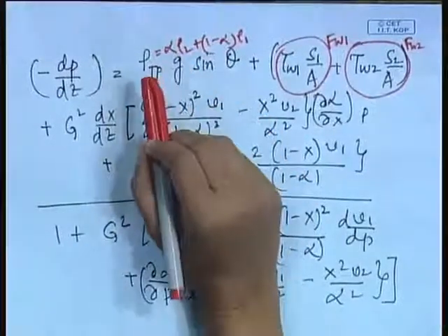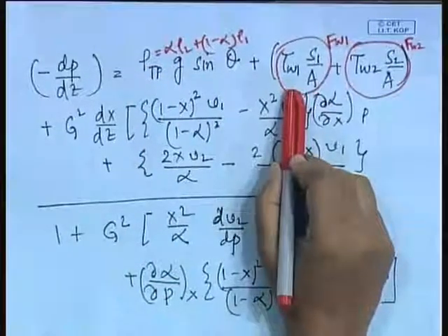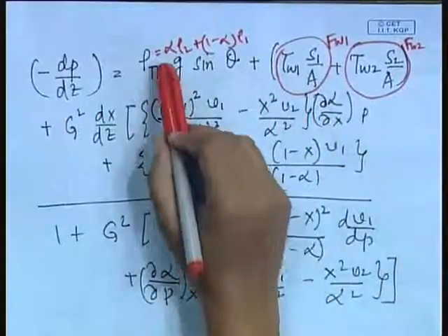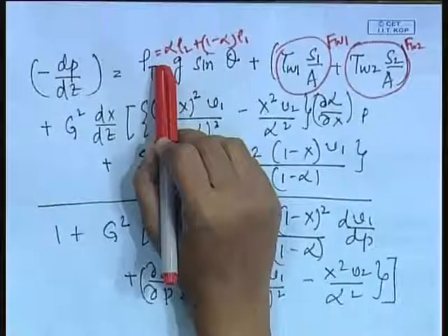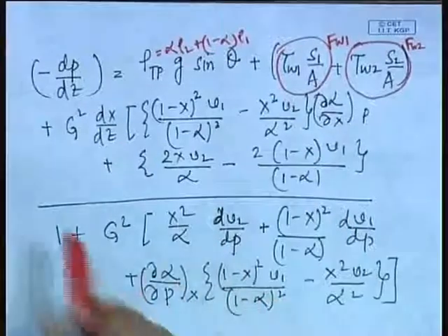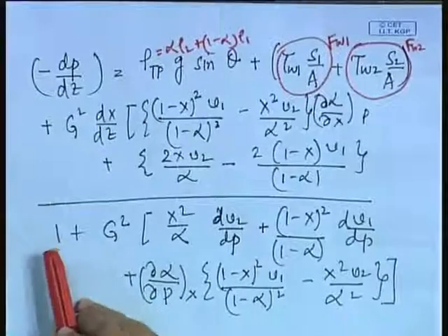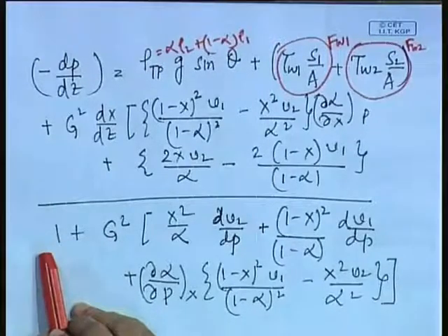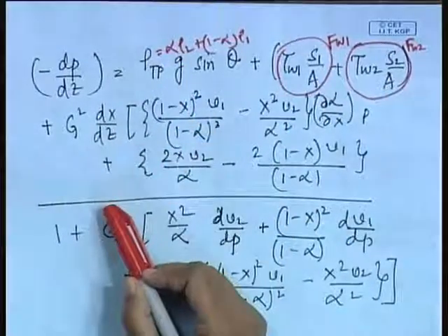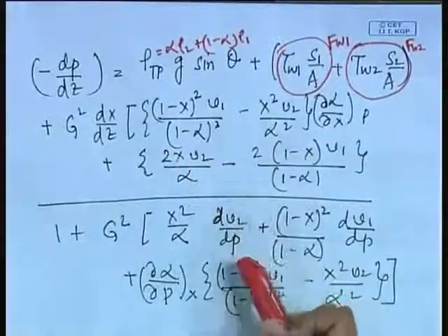So, we need methods to calculate the frictional pressure gradient component of the total pressure gradient expression, and we also need some expressions to find out the void fraction. So, apart from this particular equation, in order to find out pressure gradient, we need two additional equations, one for frictional pressure gradient and one for void fraction. And of course, apart from that, we also need relationships between the thermodynamic properties and so on.